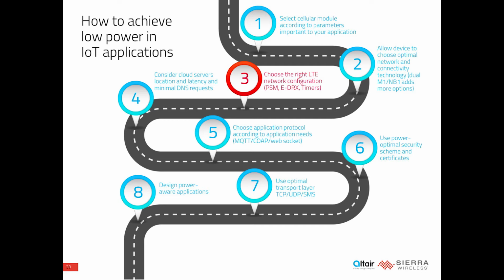The next parameter, when we work with cloud servers, is to check which protocol they use. And there is a big variety. Some people just use WebSockets, which are very simple. And we also see many IoT-based protocols coming from different vendors now. Some use MQTT, others would use CoAP. We'll find Lightweight M2M protocols. And we also see some MQTT-SN, which is a low-cost MQTT protocol. So you should take this into your power consumption consideration when you're choosing the protocol and the web service.